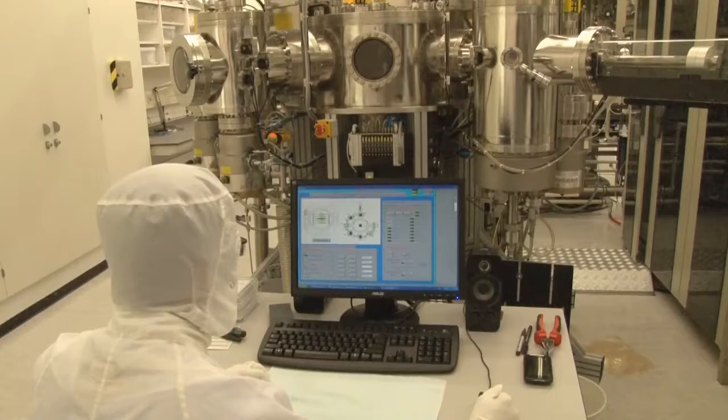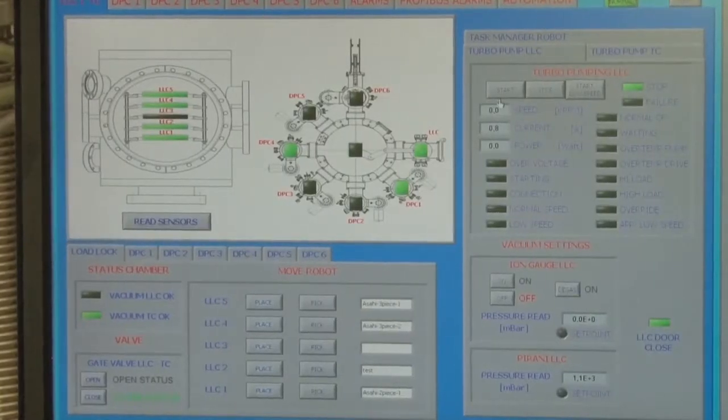Typical precursor gases in the deposition plasmas are silane diluted with hydrogen. An RF bias between electrode plates generates a plasma. The silane is dissociated and the silicon-containing radicals and ions are deposited on the substrate. Adding diborane or phosphine to the plasma makes the films p-type or n-type.